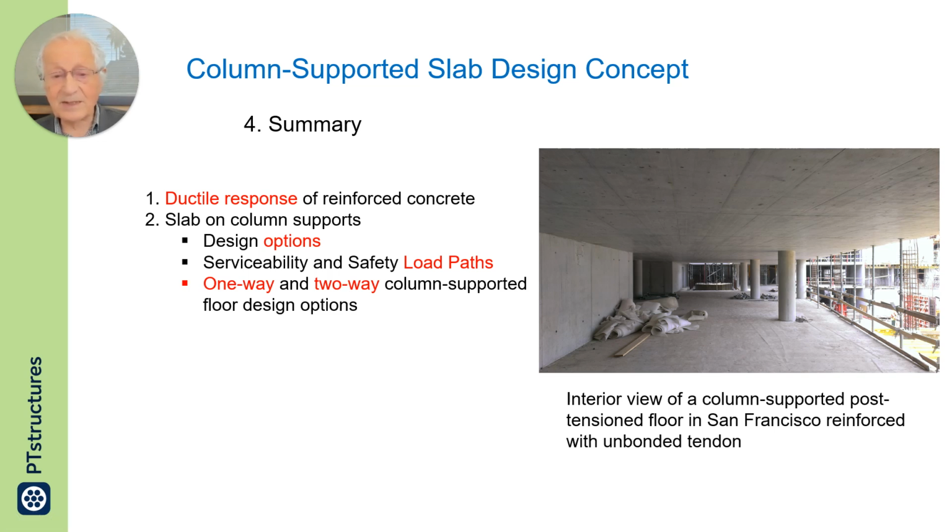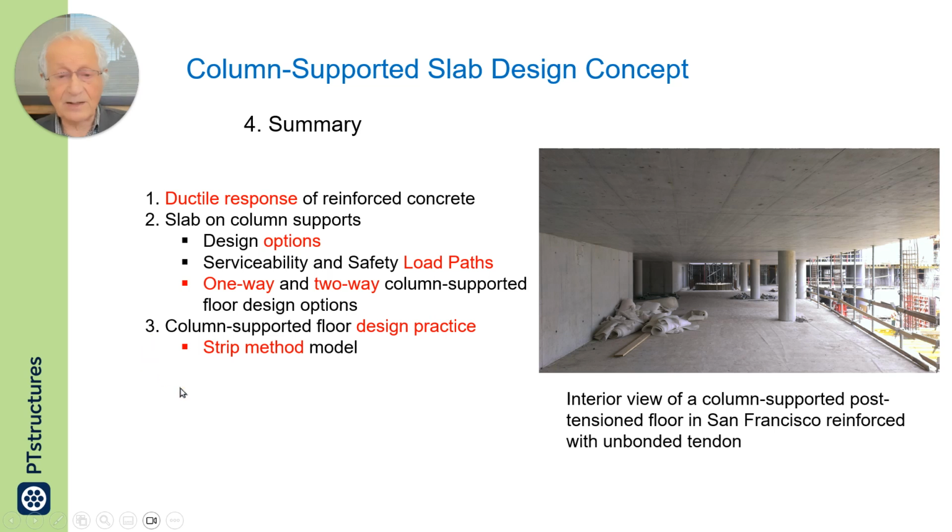Two-way system leads to two times design in this structure, once along the line of columns in one direction, and then along the line of columns in the other direction. And then I focused on the strip method, which is the common prescriptive design method in major building codes.